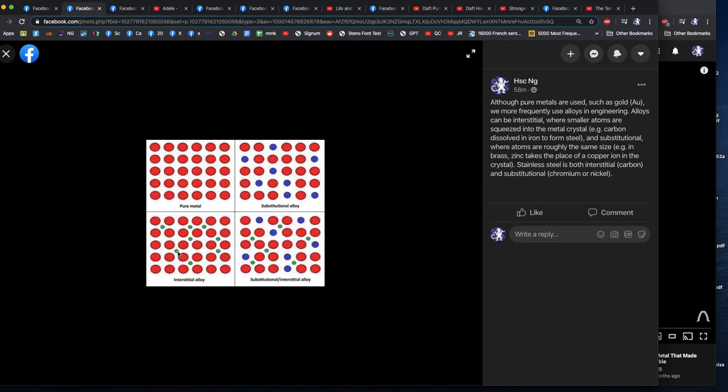That little bit of carbon here. A dislocation won't move past one of these interstitial atoms. So this dislocation is kind of trapped between these interruptions in the lattice. And the more difficult it is for those dislocations to move, the stronger the metal is going to be. We good? Does that make sense?